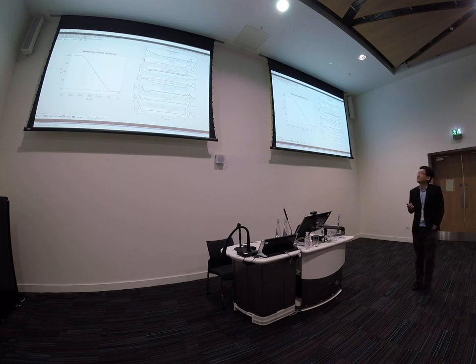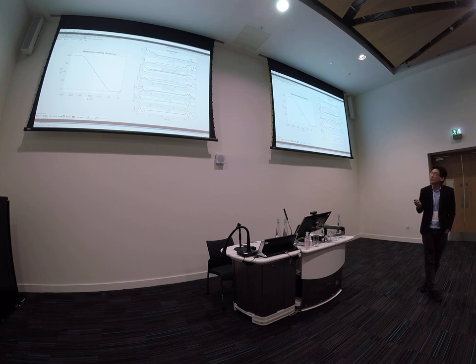Okay? So after the plane stalled, the lift is lost. We lost the lift here. And then in deep stall, the lift is regained. Drag increases. Pitching moment: pitch up, pitch down, and then stall. Deep stall. Same with pitch rate. In deep stall, I will not analyze because it's just a stable state.